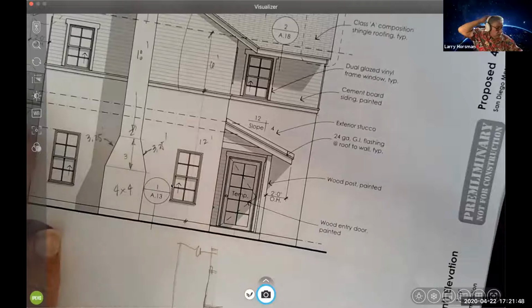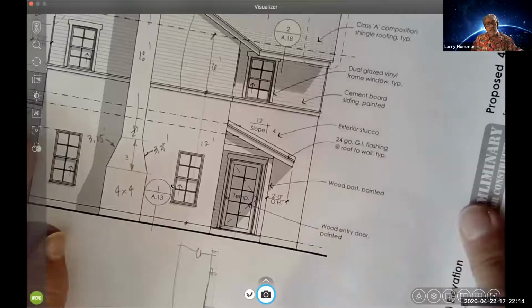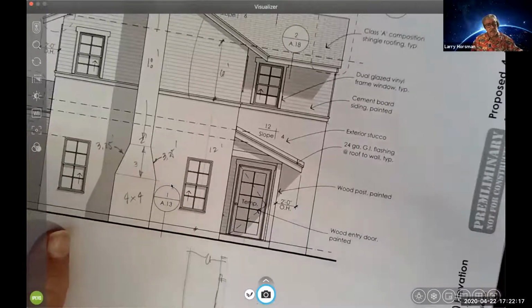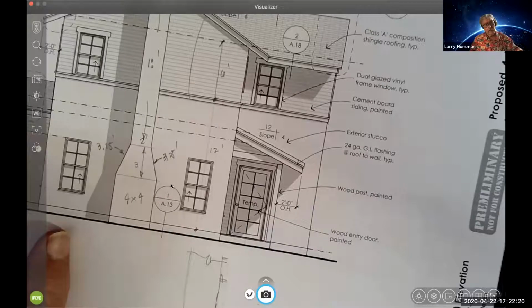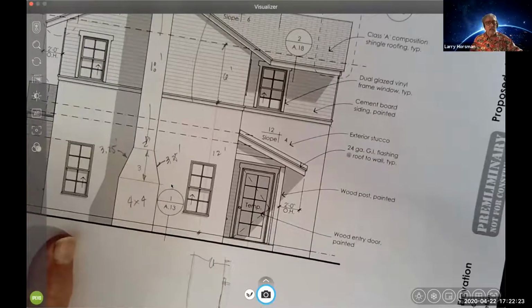And what I'm looking for, again, as part of the risk analysis, is we've got a 1-year warranty on the work we do. However, if it's a latent defect and doesn't follow some standard, I've got up to a 10-year window where they can come back and try and sue me for a latent defect built into the structure. And there's a lot of lineal footage there. It doesn't look like a lot, but flashing, depending on whether it's custom or whether I can use the standard, is pretty expensive. It would have been nice to have a detail there.